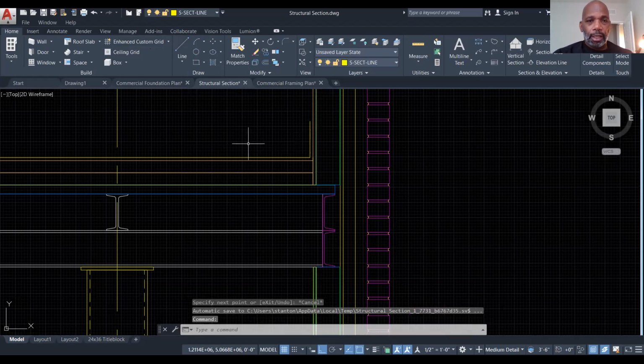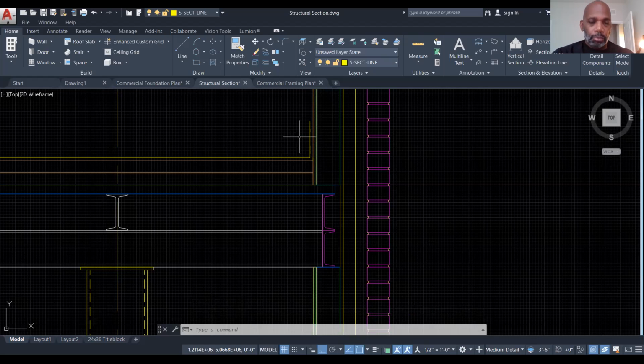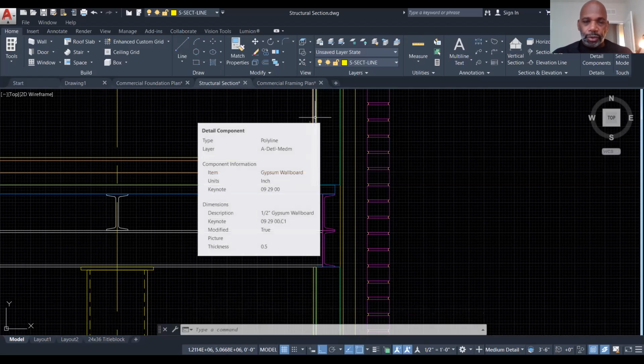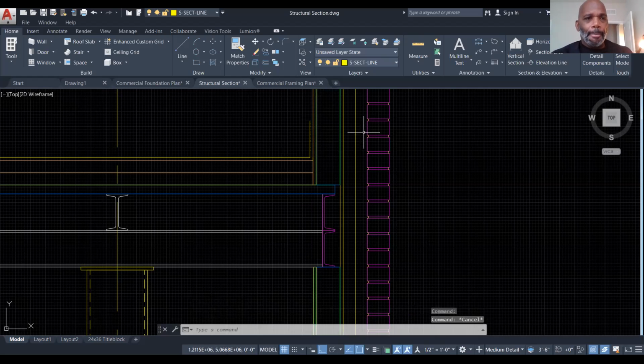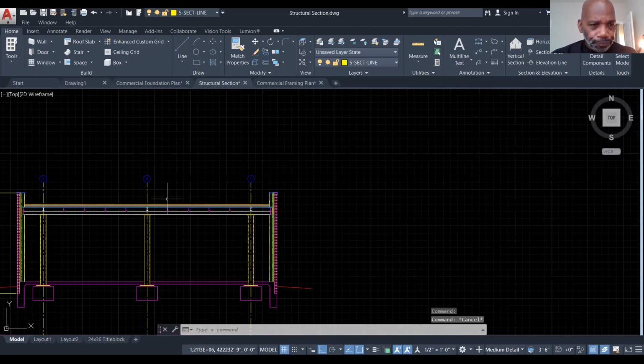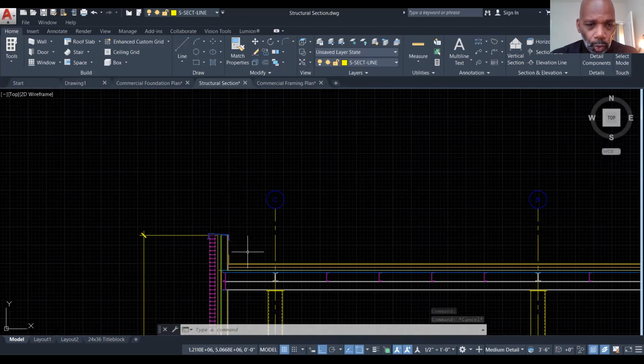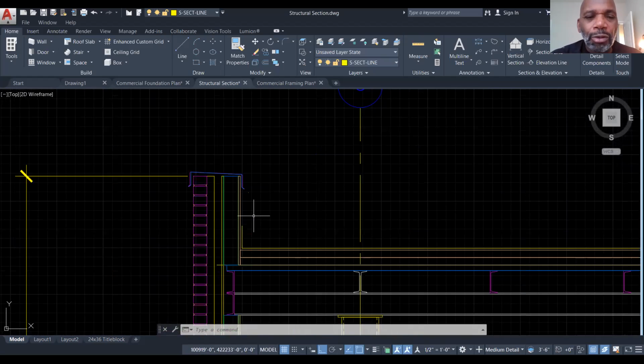Cool. All right, so now we've taken that roofing membrane and turned it up the wall. That's good. It's going to help us, right? That keeps rainwater out of this gap. Not having a gap there, turning up the wall, prevents moisture infiltration. All right, so now what we want to do is counter flash this. We're going to counter flash it.